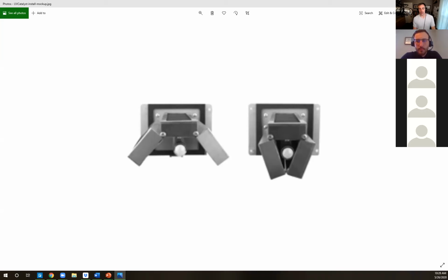For me, I was able to access it directly from the front. I'm standing in front of the furnace, my plenum is right there, and I had nothing else in the way. So we just cut straight in from the front. Whenever I come down to change the filter or the lamps on my coil application, it's right there as well. I just pop the power right off and pull the lamps and change them. But you can drop in from the top and have it hanging vertically. In the end, it's all about supply air passing by the field that's being created by this device.